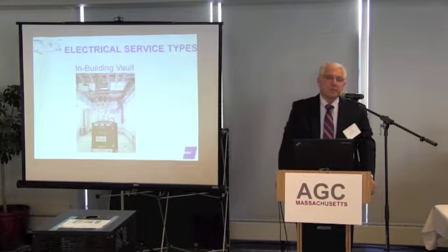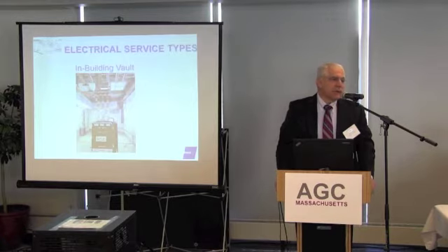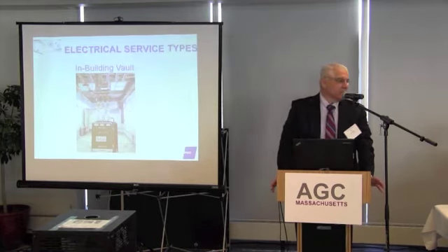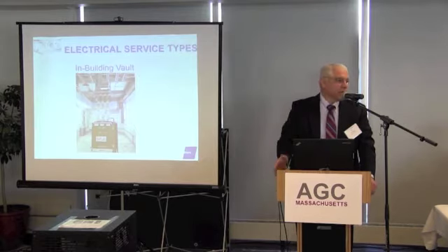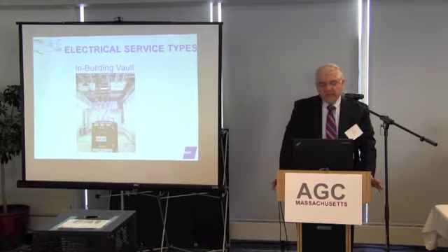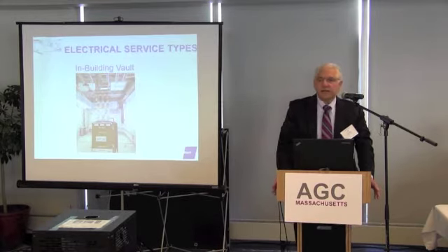And the other thing is when you're dealing with the utility company with underground distribution, like the primary conduits to a transformer, you have your civil guy do the excavation, the electrical contractor will put in the conduit. Before anything can be covered, not only do you need an electrical inspector's approval, but you also need the utility company's approval. They want to make sure that that duct bank is correct, that it's got the proper structure and the proper grounding that's needed, and the utility company has several different inspectors that you'll have to deal with.